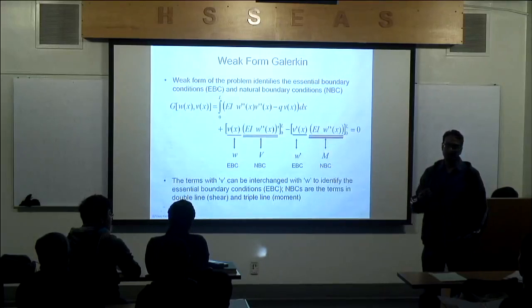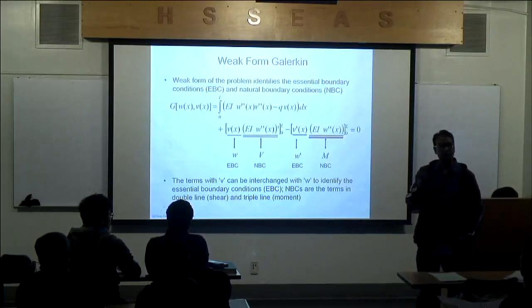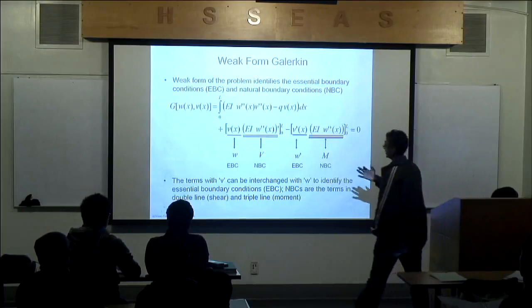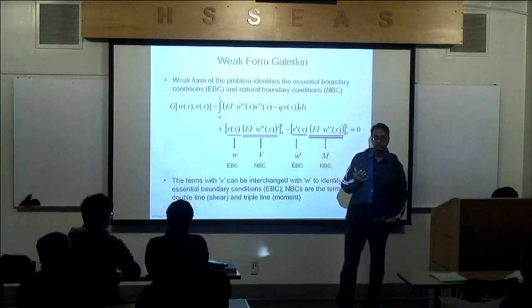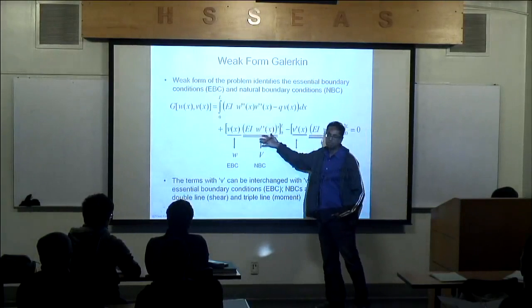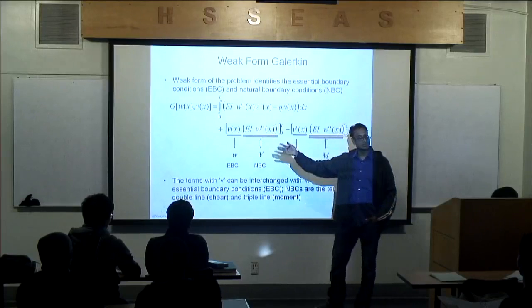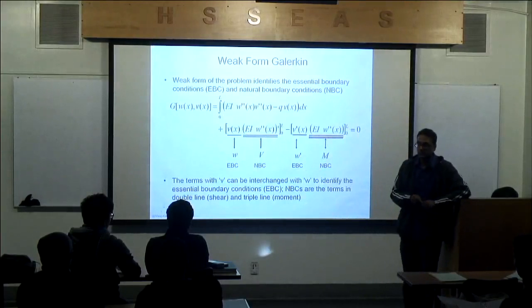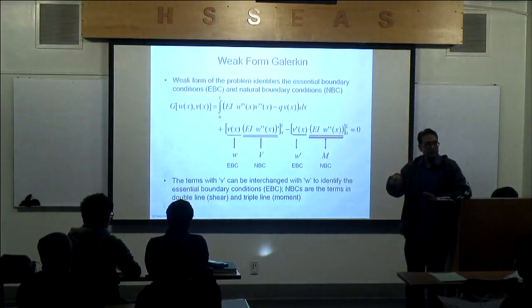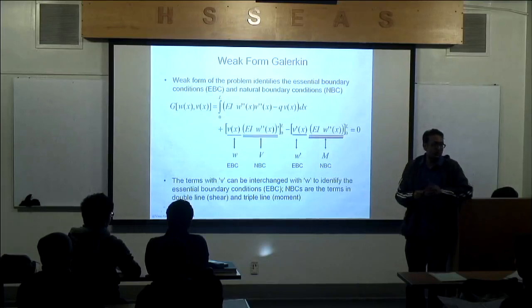To get an understanding of what the shear is, you'll have to construct an integral. You have to integrate the equilibrium equations to get the shear distribution through the thickness of the part. But to answer your question, typically if you know the value of shear, you can plug it in directly. In this case, you're right. If I were to use a quadratic approximation, it will go away. There is a gap there, and that's a great question. So if I have a shear load or something like that, then I think a cubic polynomial makes more sense. Not fourth order, which I was required before to impose, but a cubic polynomial.